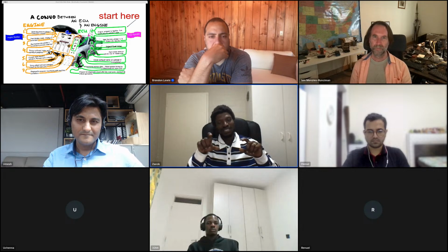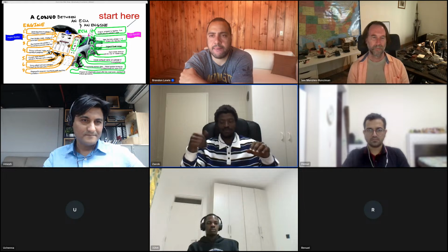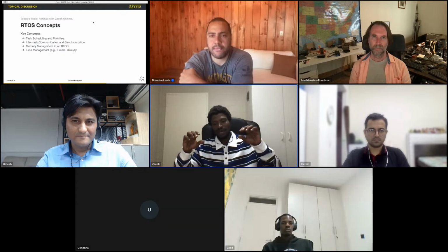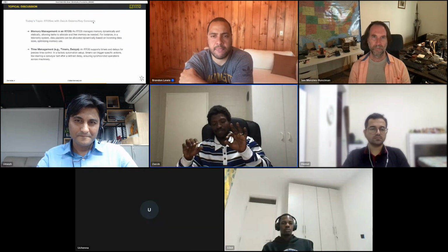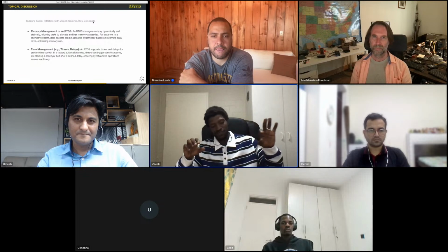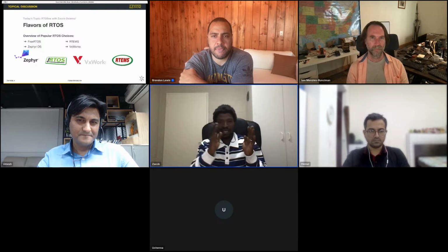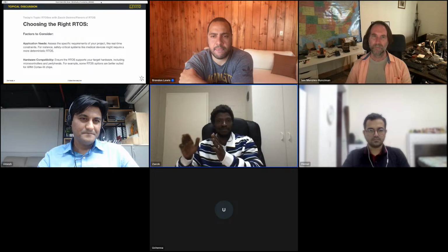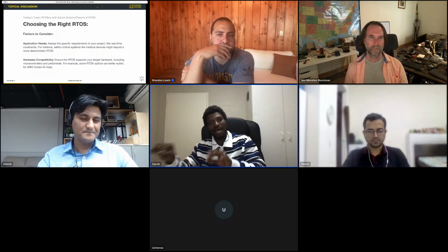So you need a CSV file, and you have an SD card to make this CSV file. The way you would use a queue is to hold these messages as they come in. For this period, for this second, the thing that I measured is this, and a queue would be able to buffer those three differently sized bits of information while you wait for them all to write the line into